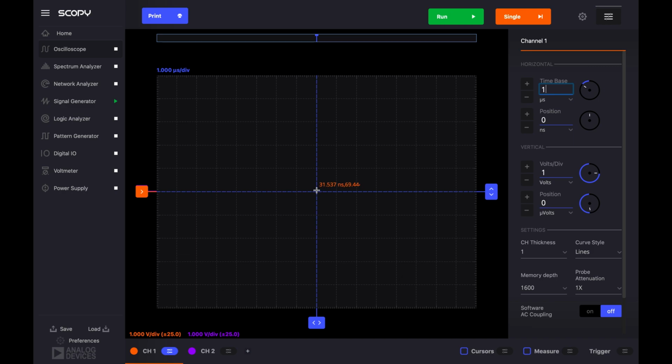So you can change basically the scaling on the x-axis. 1 microsecond is insanely fast compared to our generated signal. I want to bring this into the realm of reality. If I want to actually see one of these waveforms on my graph, and I'm zoomed in so far, I'll only see the flat part. I want to actually see the transition.